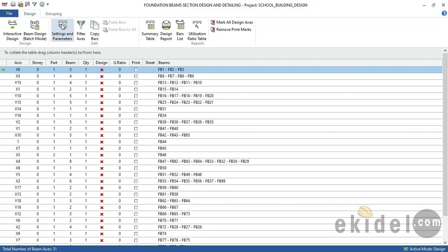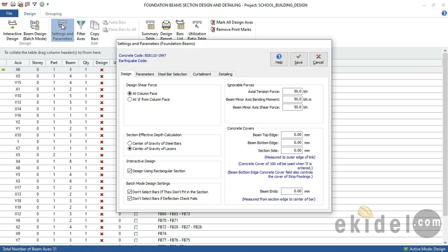So right now you have to go to this place, click first on this place. Now listen here very attentively. If you don't do these settings here, there is no way your beam will design. If you don't put these cover values, it will not design. And you put your cover values in this sequence. You put for the edge 35, and then here 50, and then here 35. If you don't put these values this way for your cover, this beam will not design.